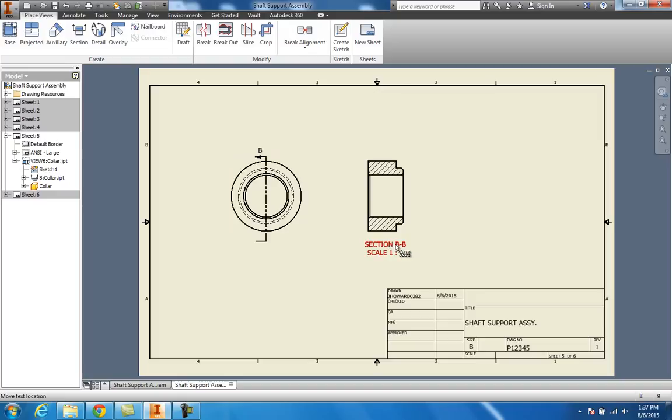You see section BB. They're saying there's a B there and there's a B down at the bottom. This arrow points to the direction that you're seeing these section lines. So you're cutting this just like you're cutting it with a knife, just to be able to see the internal parts without all those hidden lines. It makes things a little easier to understand the internal features and things of that sort. So that's the reason we use it.